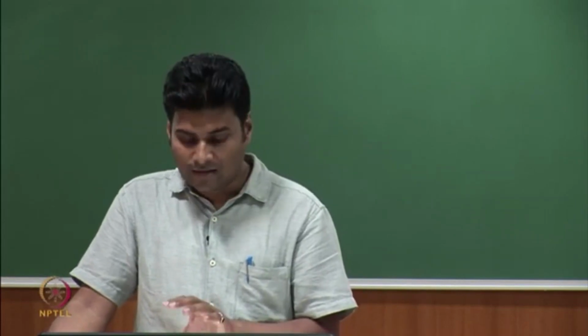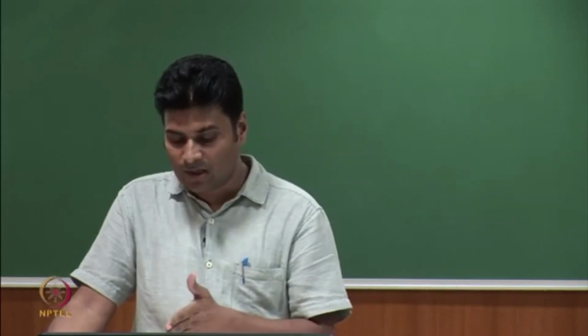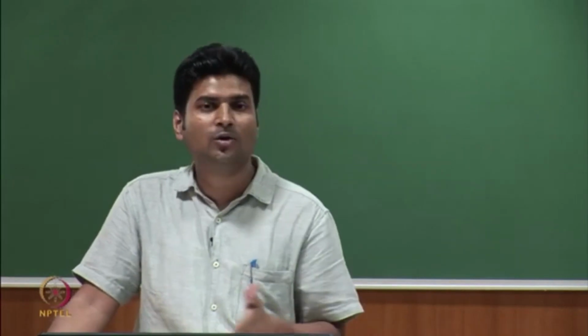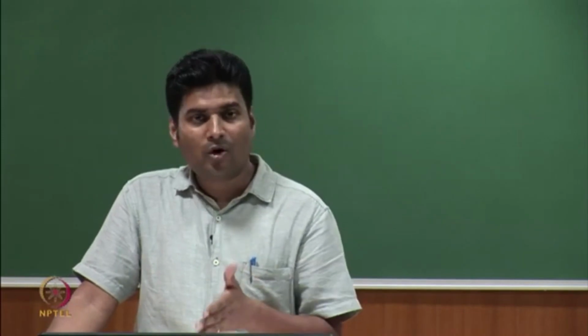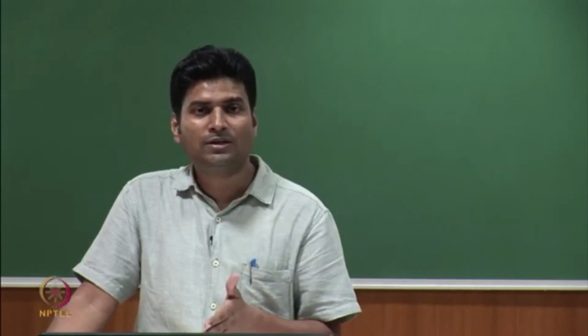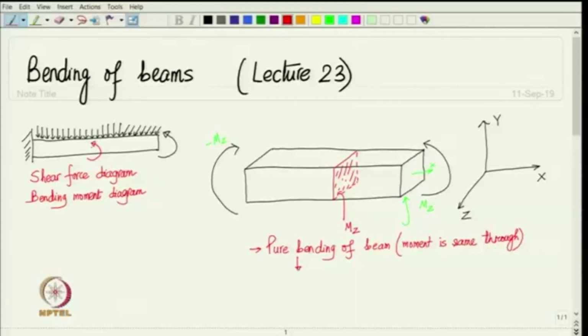Okay. And the simplest situation is when the bending moment is same all along the cross section, and we call it pure bending. When you cut the cross section, we only see bending moment, we do not see any force. Okay. So, there is no force in the cross section.